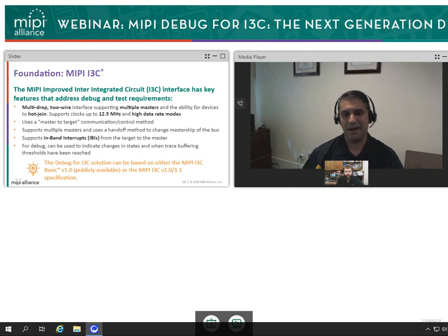And for debug, those in-band interrupts are quite important. We're able to indicate things like a change in state, or maybe we're collecting some trace information and we want to indicate back to the DTS, hey, I hit a threshold, you may want to come get the data, those kinds of things.